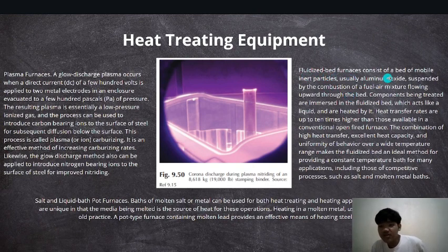A fluidized bed furnace consists of a bed of mobile inert particles, usually aluminum oxide, suspended by the combustion of a fuel-air mixture flowing upward through the bed. Components being treated are immersed in the fluidized bed, which acts like a liquid, and are heated by it. Heat transfer rates are up to 10 times higher than those available in a conventional open-fired furnace.